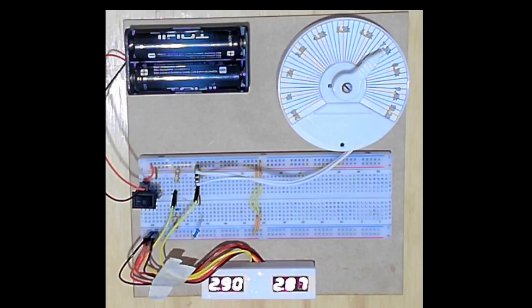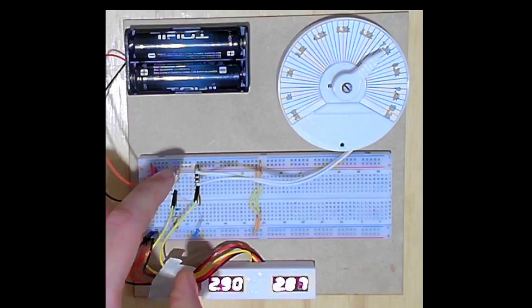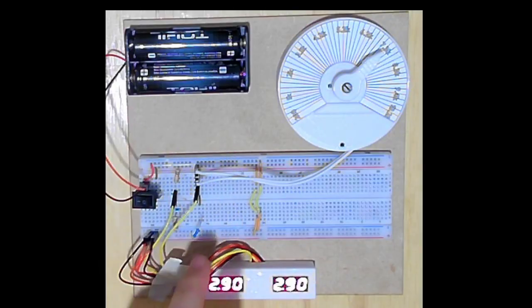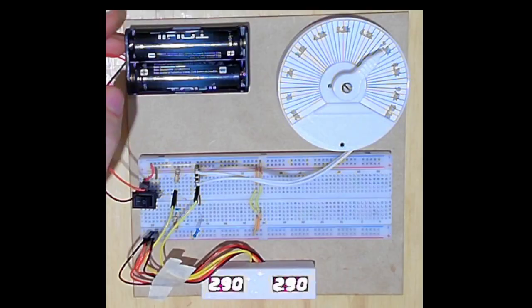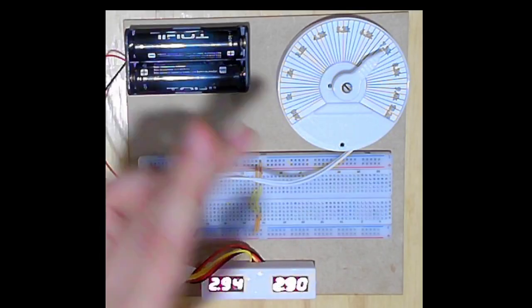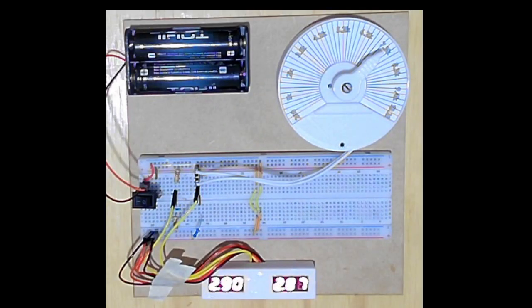The reason we need the second voltage divider and not just work with the potentiometer and this one is because maybe this voltage source is variable. So when you have the same voltage here, the relation of the resistors is the same independently of the voltage supply, right?